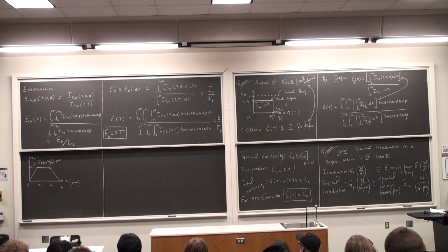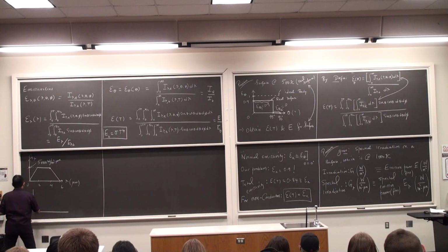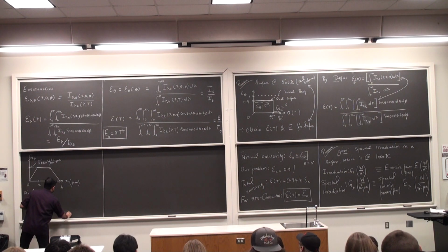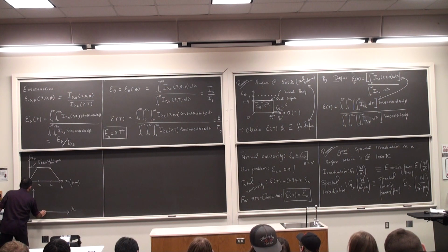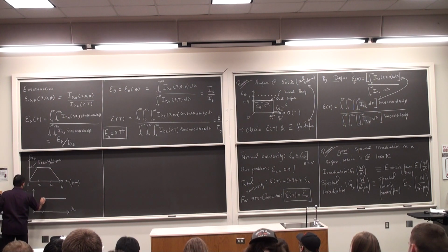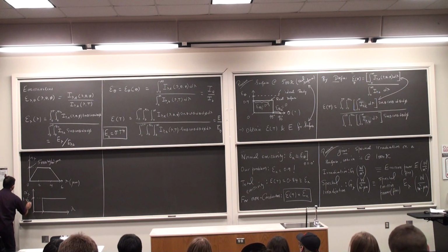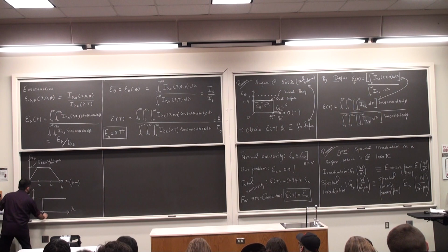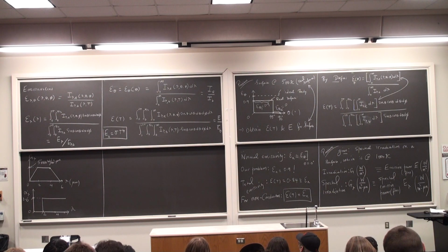I'm also given the absorptivity, the spectral absorptivity as a whole, right? This is alpha lambda, I'll write it out, as a function of lambda. Between 0 and 2, it's 0. And it's 0.6 after that, so this is 0, 2, 4, and so on, right? After that it just goes off at 0.6.